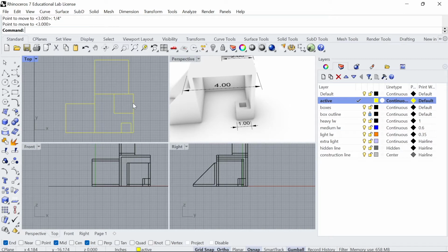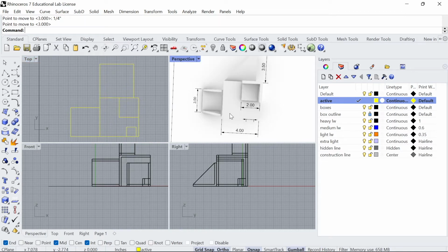Now we want to set up line weights and understand what's hidden and what's not hidden and what we end up drawing, because there's a few more lines we need to add for hidden line purposes. You want to use line weights to help you understand depth. That means usually the heaviest line is the thing closest to your eyes in that view, and the furthest thing is the lightest line.